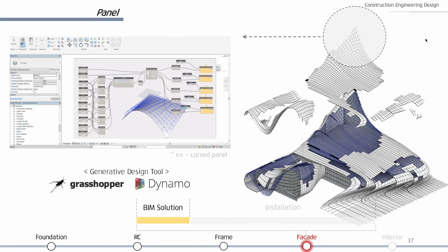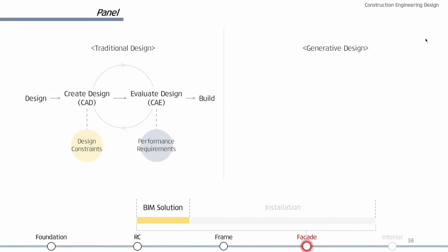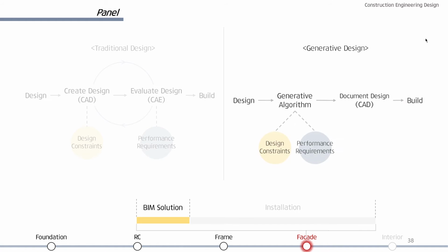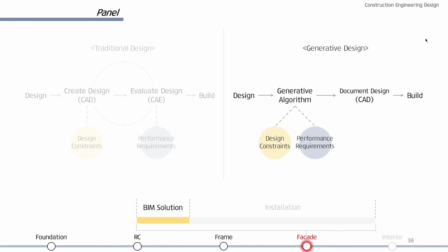This process is used as a designer that will fine-tune the feasible region by changing minimal and maximal values of an interval in which a variable of the program meets the sets of constraints. Compared with traditional design that requires a manual process and calculation of the geometry needed, generative design uses software that autonomously creates an optimal design based on the system requirements. The contractor develops a Grasshopper script to automate a process which translates each 3D panel needed within the 3D model.